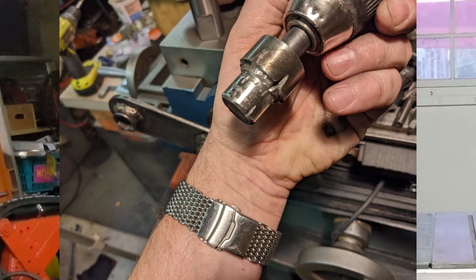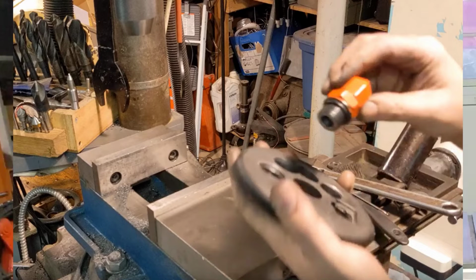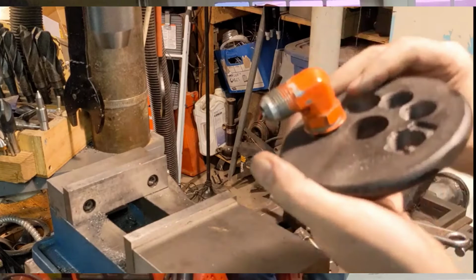For the reamer, I used the same water hardening steel rod. I turned it to the diameter and profile I needed, and after heat treating it, I cut longitudinal slices into it to act as the cutting facets. I tested both these tools on some spare cast iron just to get a feel for how well they'll work before I cut into my precious valve body. I ended up making some refinements to the reamer because its channels were too narrow and were filling up with swarf. I widened up those channels a bit and tried it again, and the second test went fine.